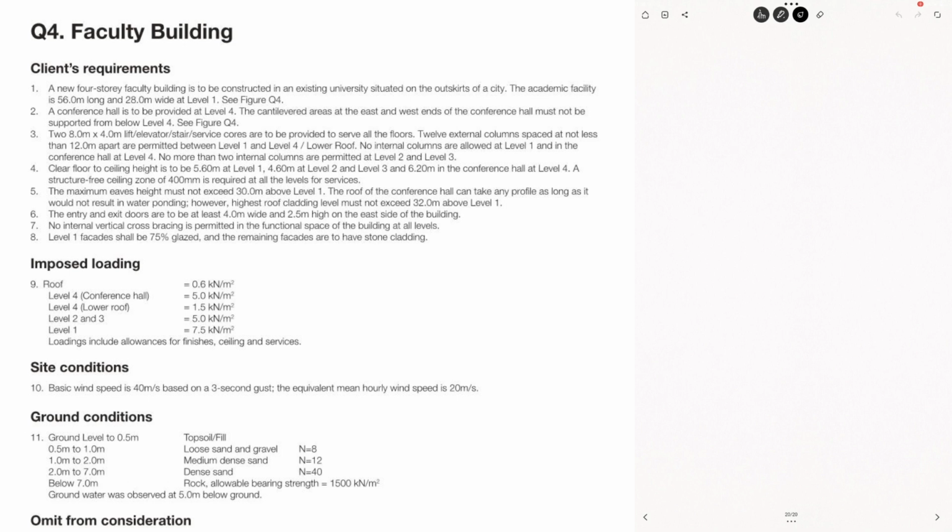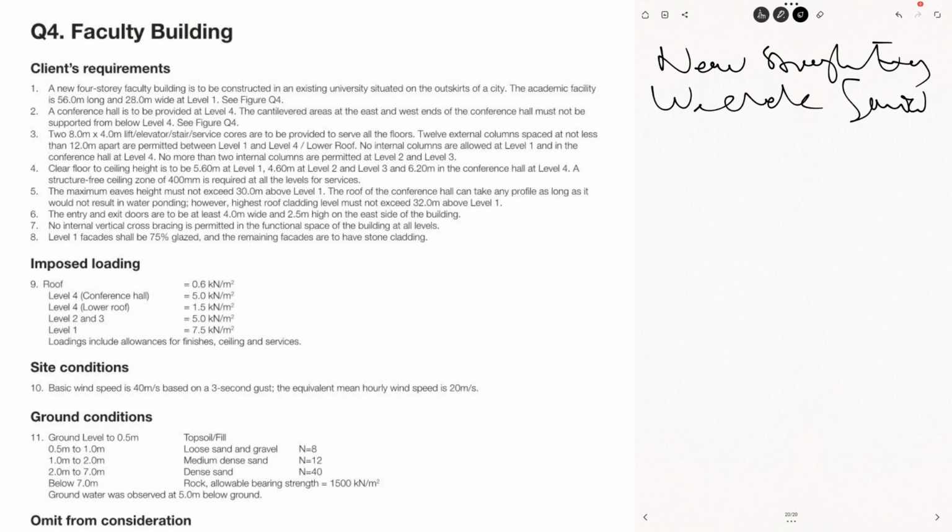And there's one final check that I'll include and that I have in my calculation template, which is the calculation of the deflection, because it also shows that not only the ULS cases are the important ones, you also need to check for serviceability. So we check now, strong enough, we check serviceability. So we calculate the deflection.